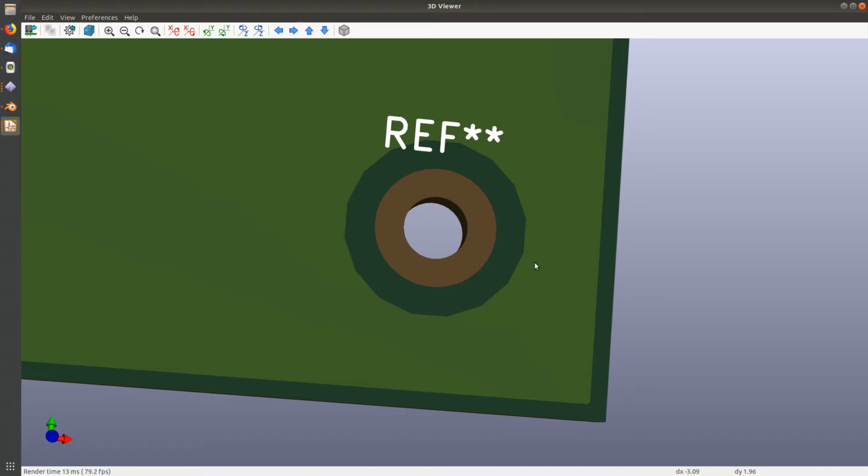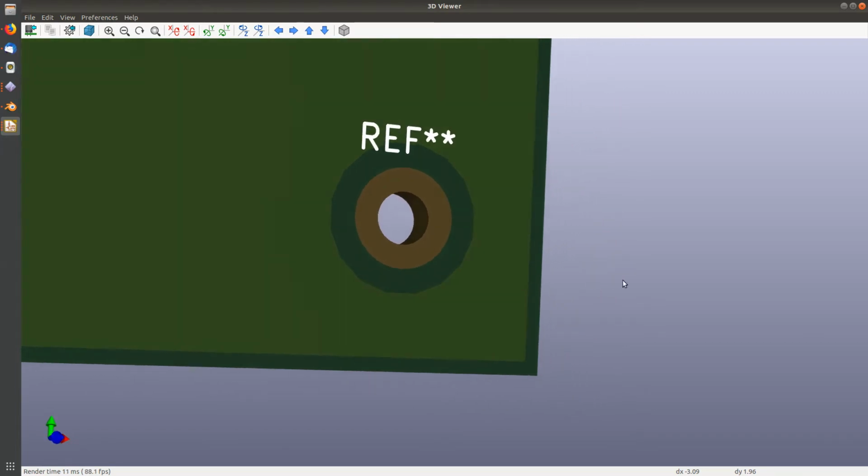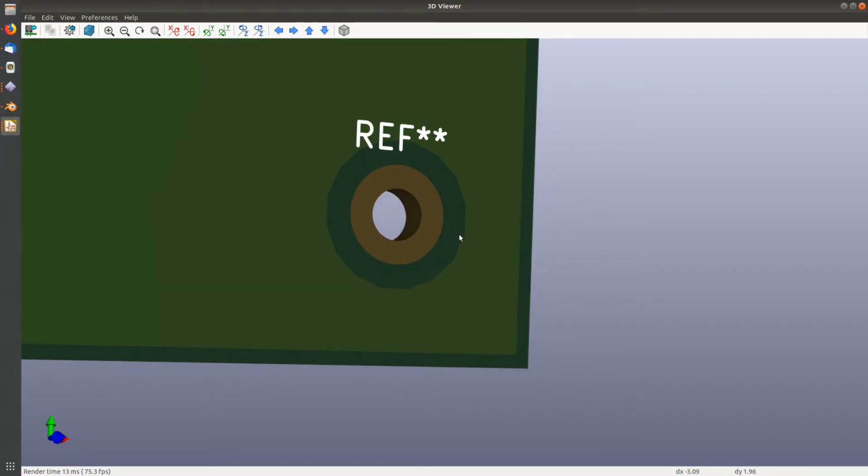Even if they were, what would happen is that remember that copper has a thickness, and if you put, you know, it's just essentially paint on that copper, the very edge of that copper is still exposed. And yes, you could end up with getting solder on that little tiny edge and get a bridge if this was plated, for example. Or it can oxidize and work its way in your board. You get chemicals on this or something like that, you can cause problems.